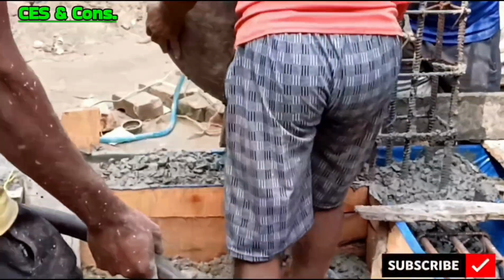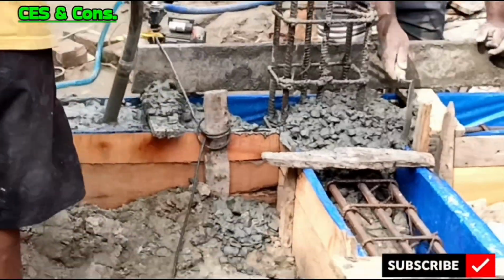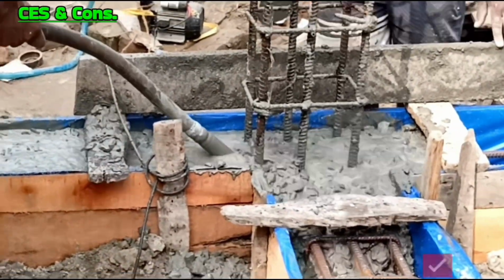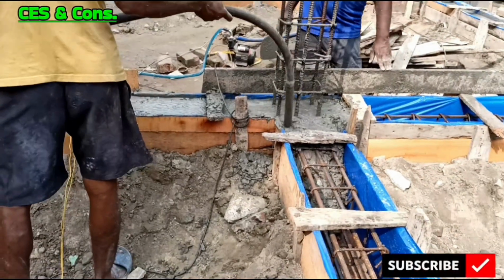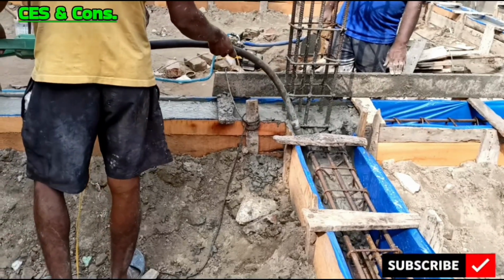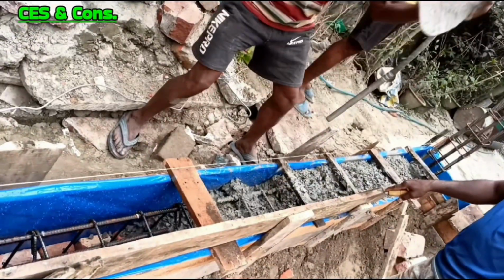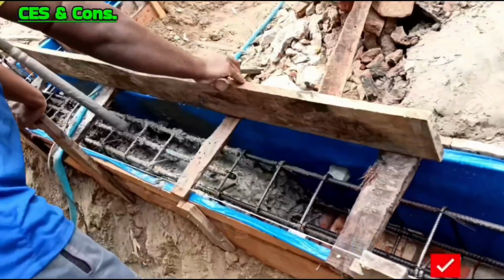Using a vibrator removes entrapped air voids from freshly placed concrete and ensures the concrete fills all gaps and corners of the formwork. It eliminates honeycombing and voids, making concrete dense, and dense concrete develops higher compressive and tensile strength. It reduces permeability by removing air pockets, prevents ingress of water, chemicals and salts, and increases service life. It ensures full contact of concrete with reinforcement steel, provides stronger bond between steel and concrete, enhancing structural performance.